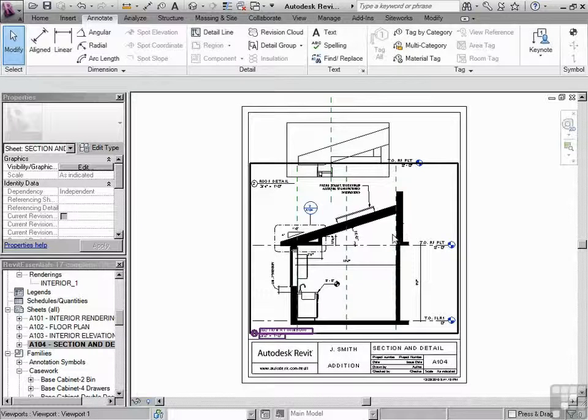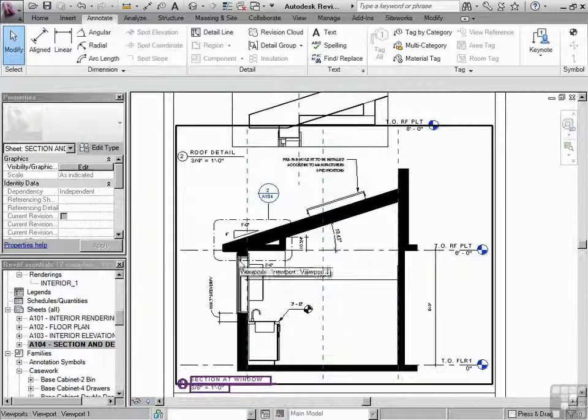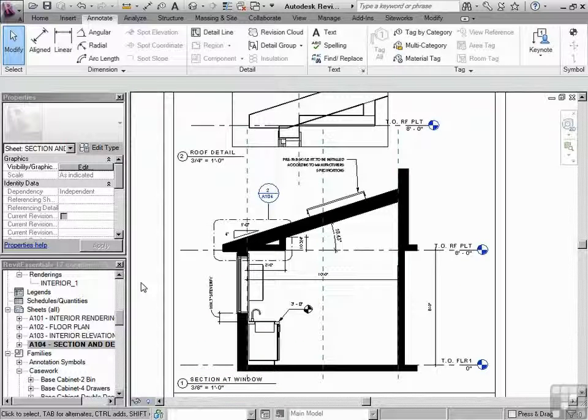You'll notice that, for instance, when we blacked out the walls here, we didn't hatch it. We just changed the way the style behaves. The hatch is built into the object. If you were to look at brick, the brick material has a brick hatch built into it. So if you look at it in elevation, it's hatched. So really, hatching is not something you're going to be doing as far as flooding a space with hatch. It's a little bit different.